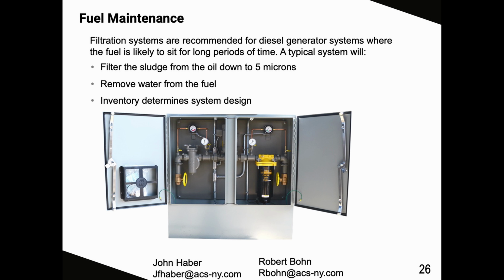It will filter the sludge and water in the oil down to 5 micron before returning it to your tanks. This can be used for single tank or multi-tank applications, and the inventory in your tanks determines the system design for your filtration.